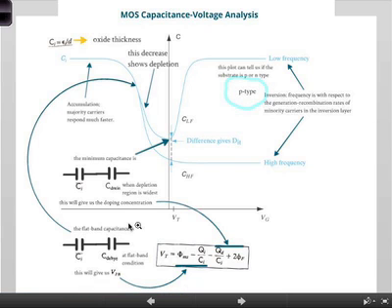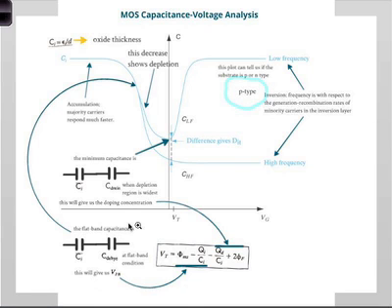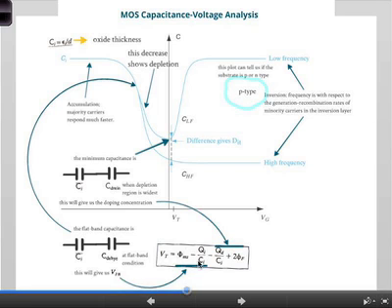So what we are able to do from this plot is essentially the following. We are able to estimate the terms that go into the threshold voltage. So we can experimentally determine what the threshold voltage is without even having to actually run the MOSFET as a device. Okay? Because the first two terms give us the flat band condition.